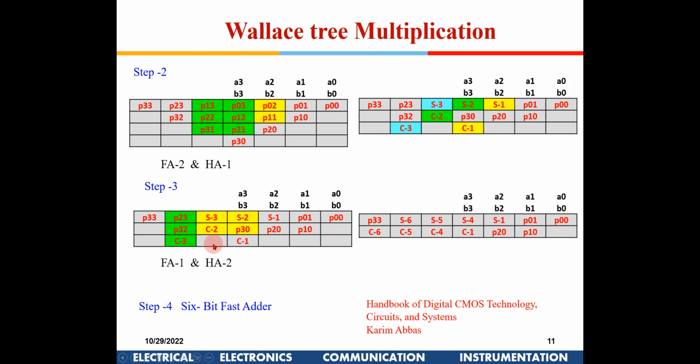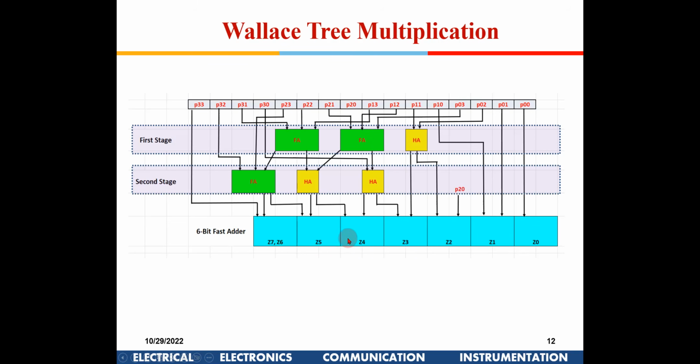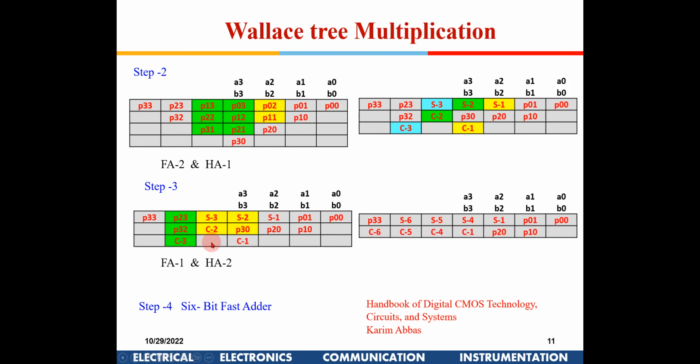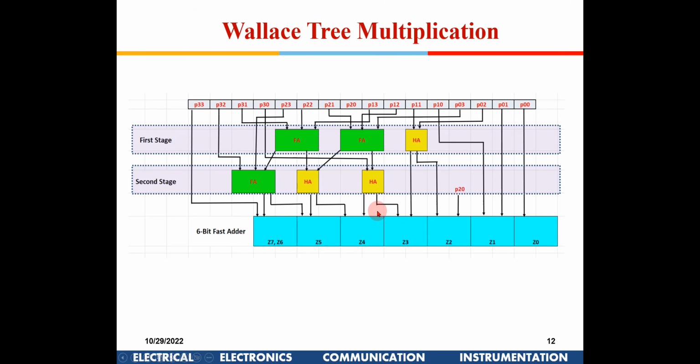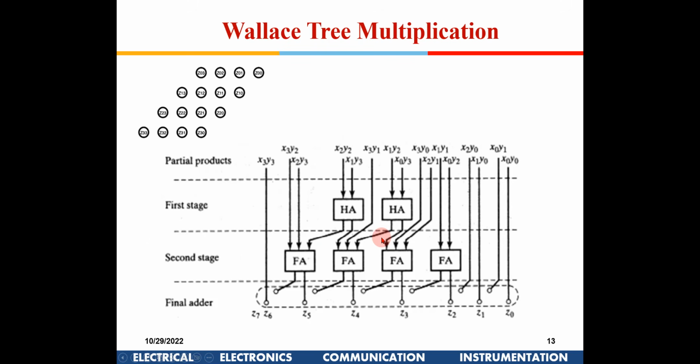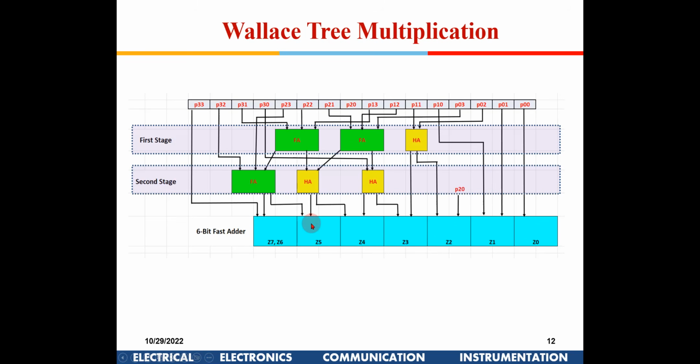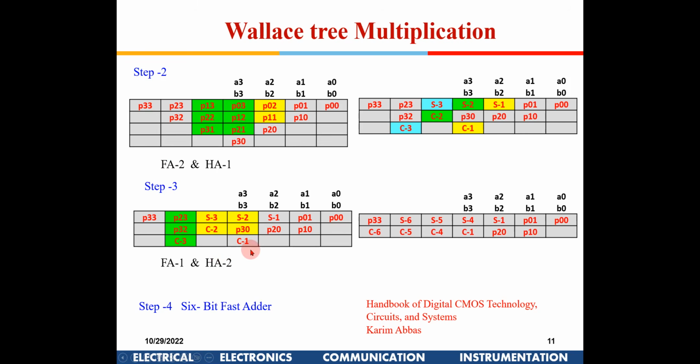No, but ultimately you require 2 bits as a balance out here, because you are going to finally put a full adder in the bottom here. You don't want to underutilize this fast adder, right? So that is the reason. Always 2 bits should remain. So if I use it, then I'll have to give one input as 0 in that particular case in this fast adder. So you have to take care that you don't land up in that situation. Okay, so that is the reason.